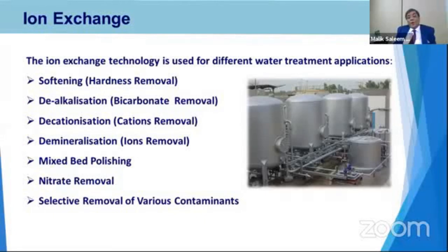If we further need polishing, we can go for mixed bed polishers or EDI to make the water purer. For high pressure boiler use, where we have pressures of 40, 80, 100 bars, we require feed water conductivity of less than 0.2, which is almost just traces of TDS, around 0.01.